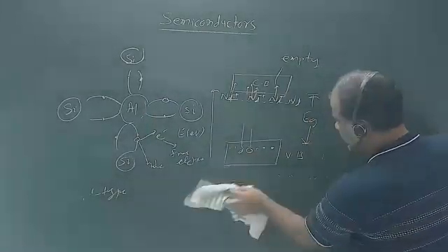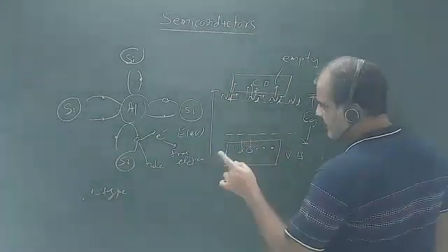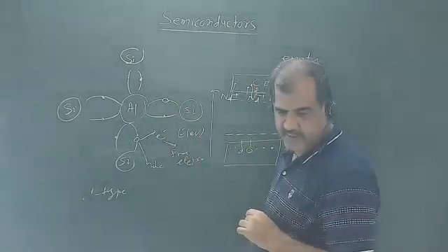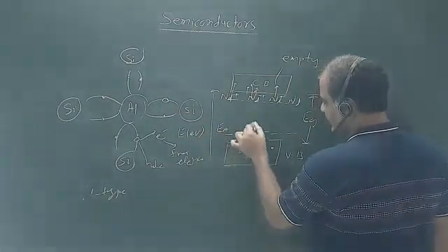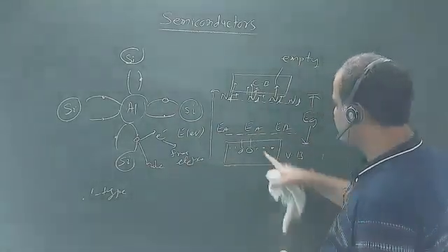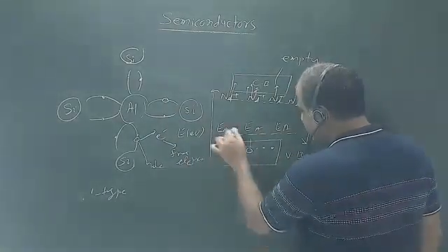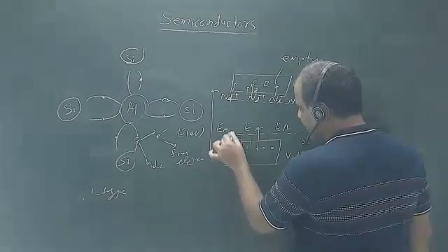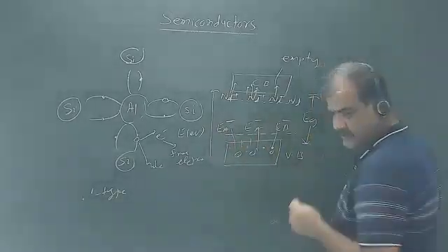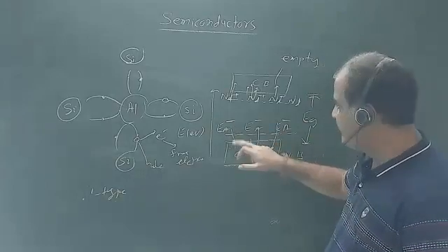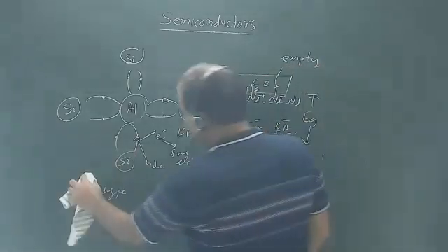And if I see the energy level of these acceptor atoms, because they will accept electrons, that's why they are acceptors. I'm representing them by EA. The energy level of acceptor atoms is very close to the valence band. So at room temperature, these atoms will capture electrons from the valence band. They will generate holes in the valence band, and they will become negatively charged. That's why they are acceptor ions. In the n-type case, they become donor ions.